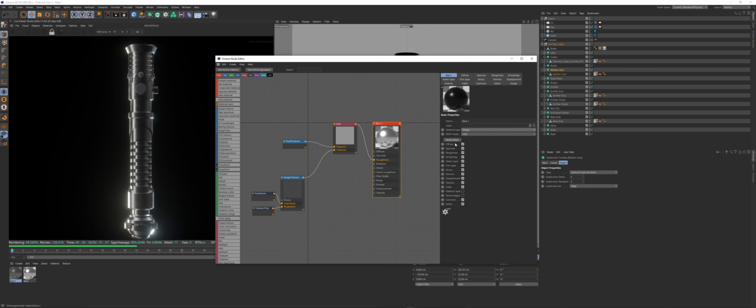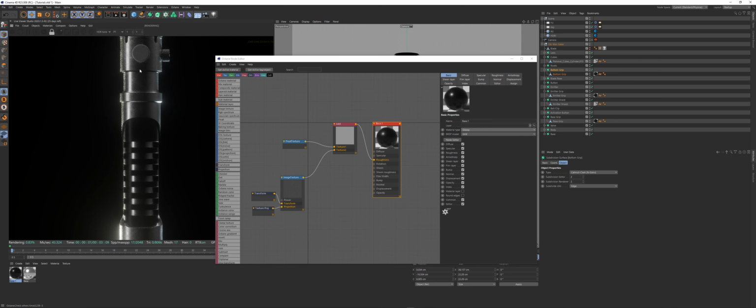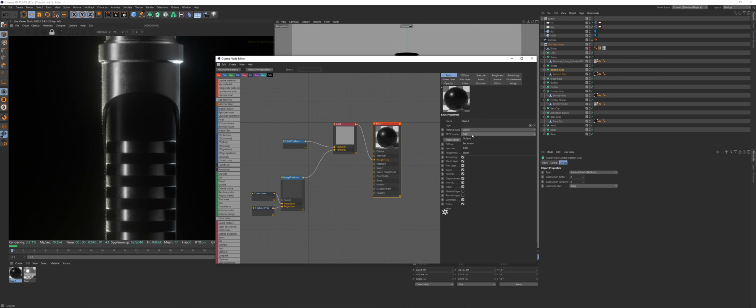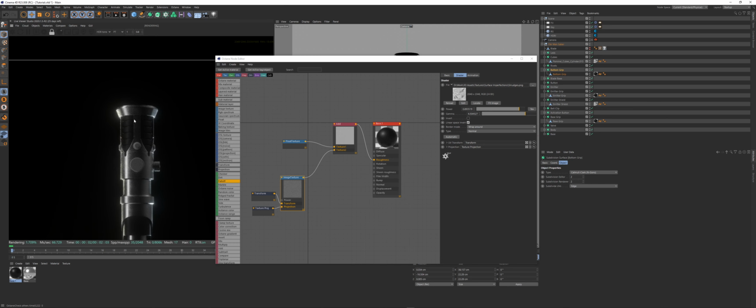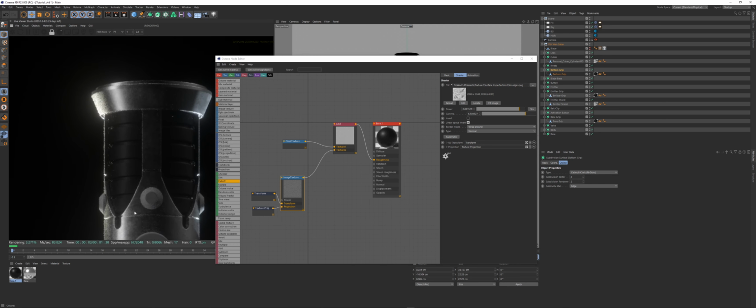So I'm gonna switch this to glossy, and I'm gonna come off GGX and loosen up them kind of reflections, and then I'm going to bring the power up on the surface imperfection. Maybe going to bring the scale down. Going to zoom in here.